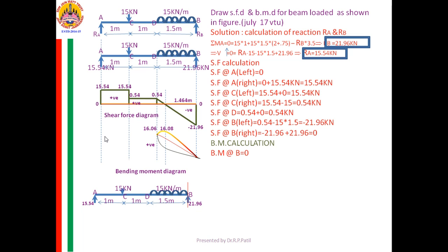When I see, I want it at that line, the red line, that is the B. Better I am taking all the loads on the right side. Nothing is there, no load on that part. Therefore, bending moment at B equal to 0.